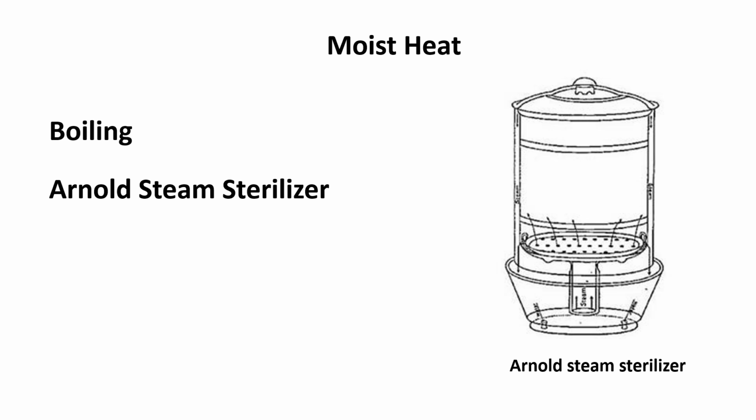The inner cylinder has a perforated bottom, as you can see, through which the steam may enter. The steam comes from the small chamber below the copper bottom, which contains water which is boiled. The peculiarity of this type of sterilizer is that the steam which escapes from the sterilizing chamber condenses beneath the outer cover and falls back upon the chamber in which the steam is generated.